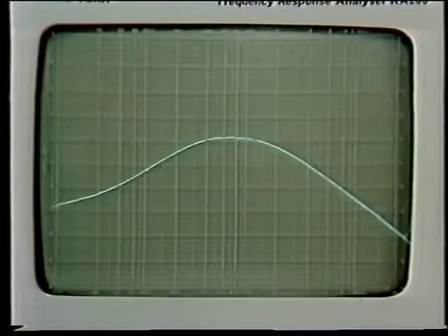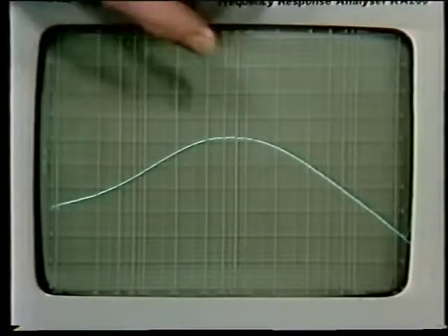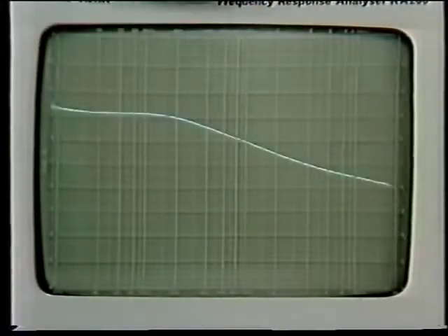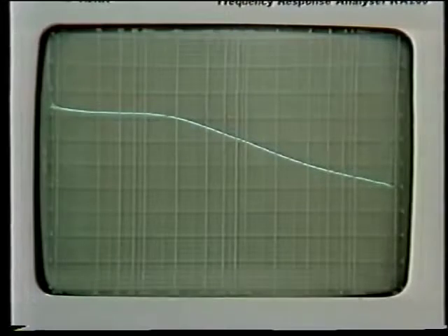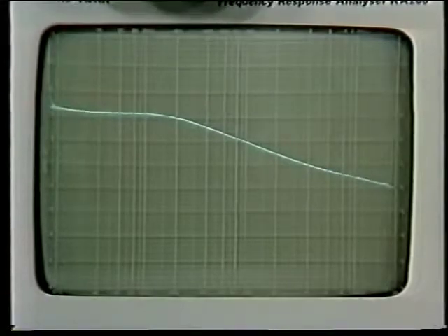I've already done the phase sweep and stored it. Let me just show you. Now, this is the frequency for which the phase change around the loop is 0. It's the frequency for which the gain has a magnitude of 1. Let me bring back the magnitude display. And as you'd expect from the unit, it turns out to be about 700 Hertz, the frequency at which the circuit oscillates when the loop is closed.